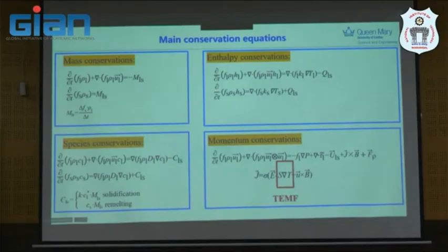The solid phase is stationary, which means the velocity is zero, and the liquid phase is moving, and the velocity is solved by this equation. And this one is the thermal solute buoyancy force during the solidification, which will drive the liquid flow in the simulation domain.